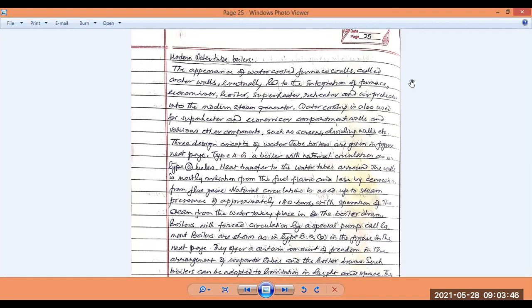Superheater: here, after formation, the steam is superheated. It is at around 100 or 110 degrees centigrade, just around boiling or slightly more than the boiling of water. But you are heating this in the superheater so that it goes up to around 560 or 580 degrees centigrade, so that no moisture content remains present, I mean no water content remains, but everything is converted to steam itself.